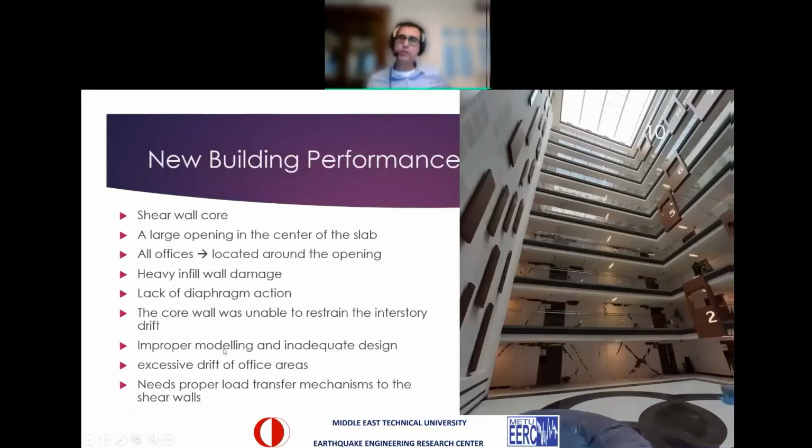Most probably the problem was improper modeling and inadequate design, because if you model on the computer with infinitely rigid diaphragm floor action, on the computer you see a perfect behavior against earthquakes, but in reality it is not the case. You need a proper load transfer mechanism to the shear wall. You have to transfer the earthquake load to the shear walls.